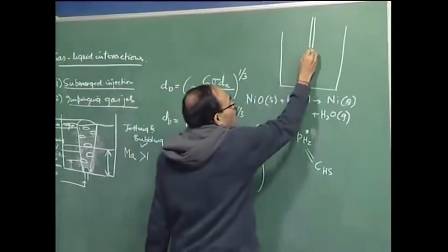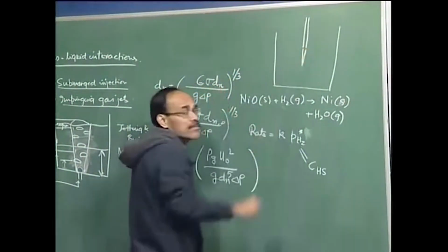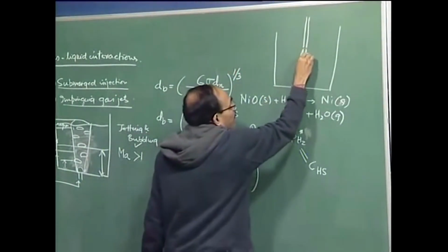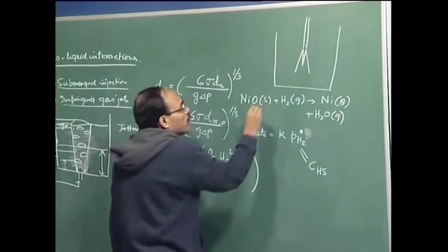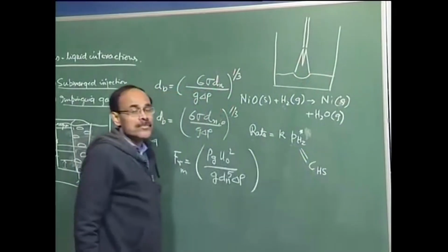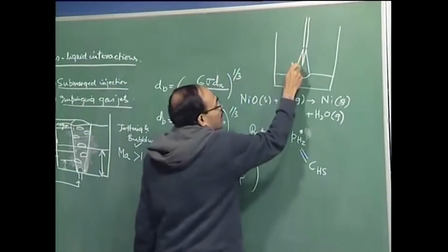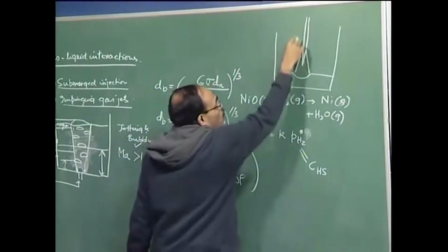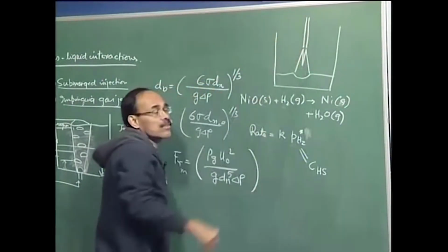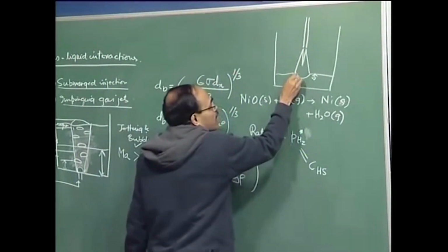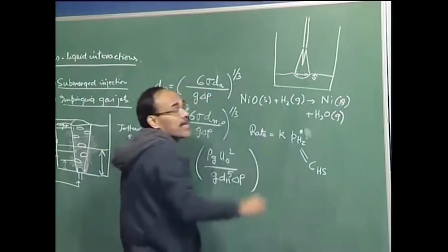There is a core of the jet, and following the core you have large scale entrainment, so considerable widening of the jet takes place, and this widened jet ultimately impinges here. By controlling the height of the nozzle, you can control the depth of penetration, as well as the impinging area itself.